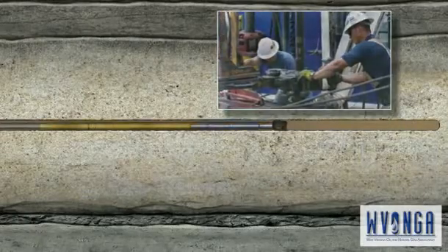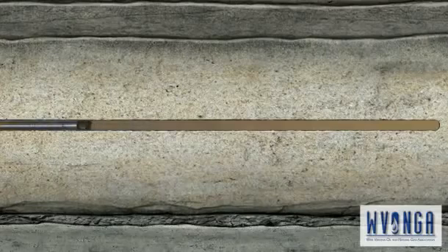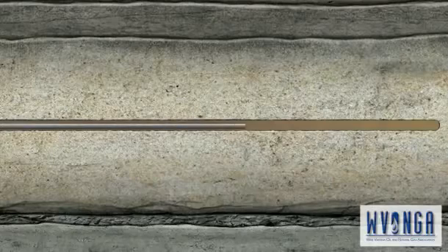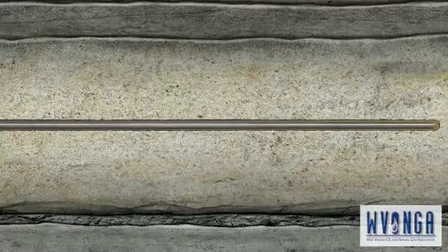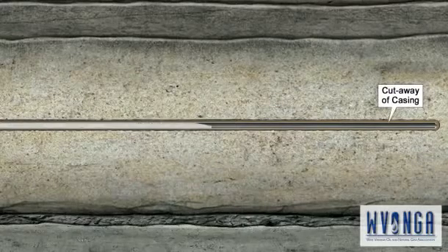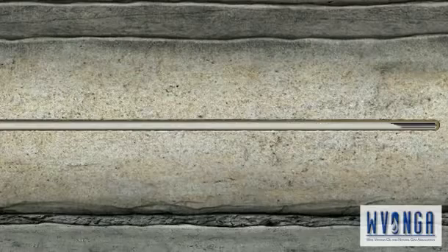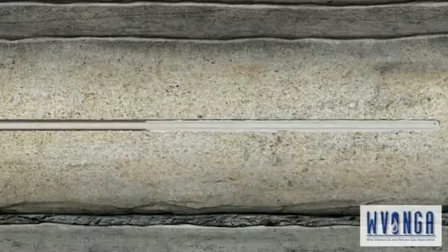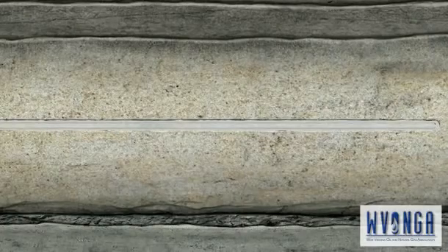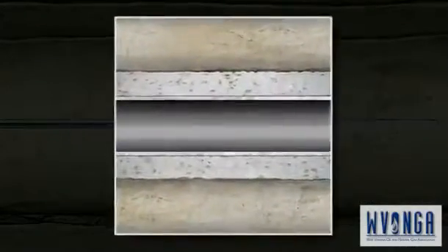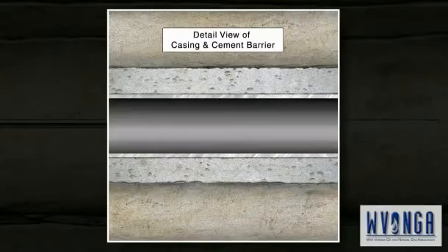When the targeted distance is reached, the drill pipe and bit are removed from the wellbore one last time. Production casing is now inserted into the full length of the wellbore. Cement is again pumped down the casing and out through the hole in the casing shoe, forcing the cement up between the casing and the wall of the hole, filling the open space known as the annulus. Casing the well is a very important process because it permanently secures the wellbore and prevents hydrocarbons and other fluids from seeping out into the formation as they are brought to the surface.